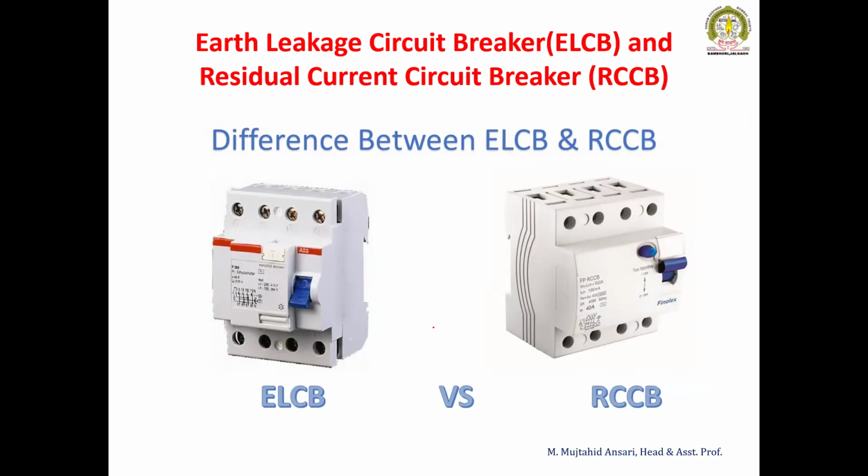Similarly, there are two different circuit breakers. One is the ELCB, earth leakage circuit breaker, and the other is the residual current circuit breaker. The difference is in the case of an earth fault, say for example, this is an appliance and somebody is going to touch over here. Therefore, the current is going to flow from the metallic body to the earth. So the same current is not going to flow through the incoming and outgoing wire.